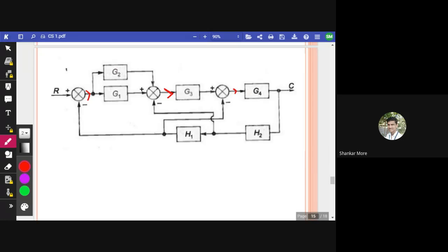No. All right. Fine. So see, guys, I have already told you there should not be a feedback loop coming after the X. So here it will be correct if you place it before G4, and after that summing point. There is a summing point between G3 and G4, isn't it? So after this summing point, you have to place X.